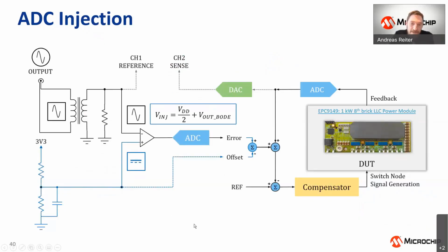The best implementation, however, takes a little bit of additional circuitry. So what we do here is still we build our voltage divider to create VDD half, or half of our ADC range. But then we use an additional op-amp, a differential op-amp, which is adding the offset to that AC signal, and then the AC signal is adjusted roughly in the range of plus minus 1 volt max, so that it nicely operates around that offset.